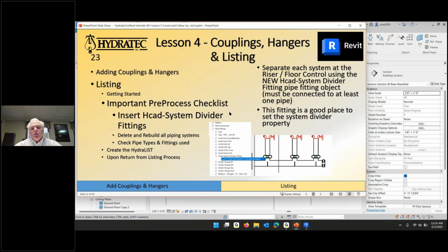This is going to the definition of a Revit system. They've got cold water piping, hot water piping, drainage piping. The cold water and the hot water are all tied together through a water heater. So they're all one system, but Revit intends for them to get broken up into separate systems.